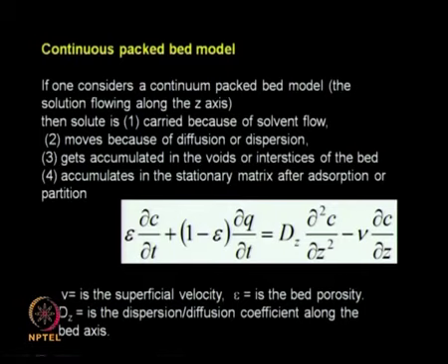So this is a continuous packed bed model, the solute is moving from left to right along the z axis. The solute is carried because of solvent flow, carried because of diffusion along the axis of the tubular bed or dispersion, gets accumulated in the voids or interstices of the bed, and is also present adsorbed onto the stationary matrix.